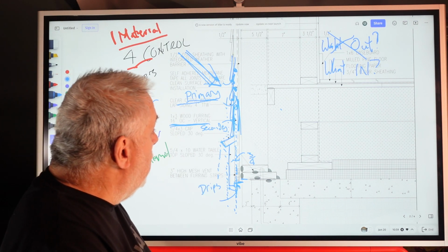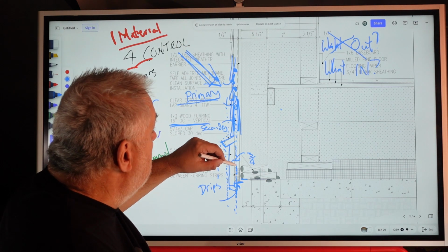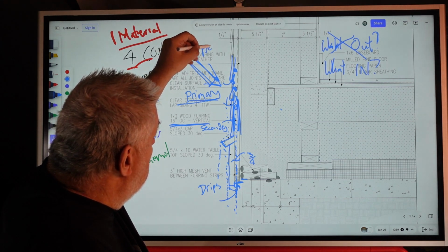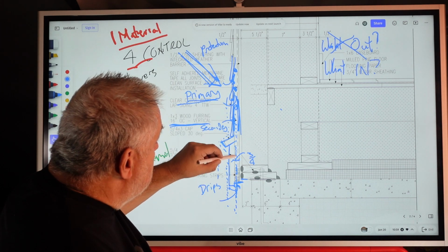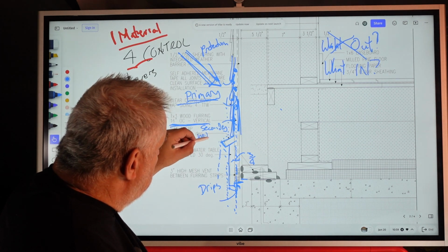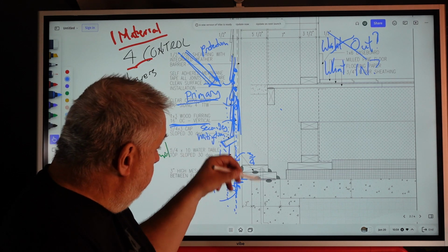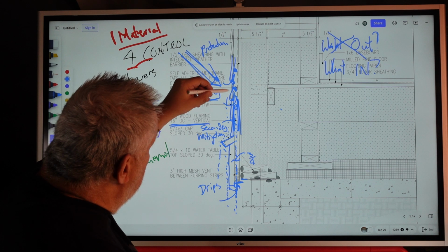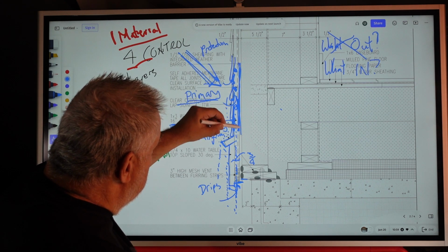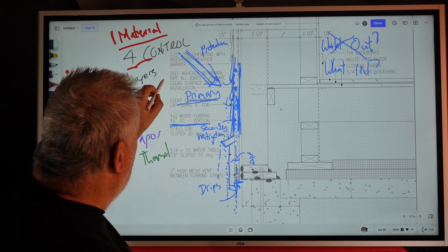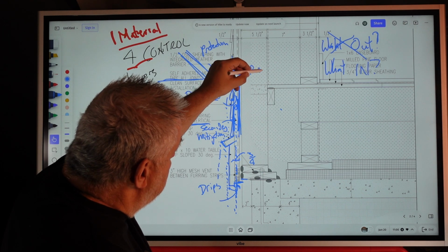So if I look at this and I want to apply the words, the outside cladding system is my protection. The secondary drainage space is my mitigation, right? If water gets in, how do I deal with it? And then, of course, the face of, in this case here, we used zip sheathing and all the joints were taped. That is our prevention.